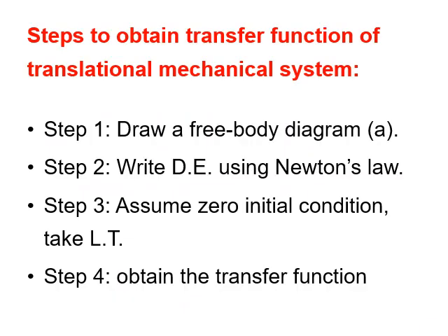We are going to follow few steps to get the transfer function done. The steps are given here, and we will see them in the coming example after a while. Step number 1, it's to draw the free body of the system you want to find its transfer function. Then after that, we will write the differential equation by the help of Newton's law. Then we will assume initial condition when we find the Laplace transform of the system, and after that we will obtain the transfer function.